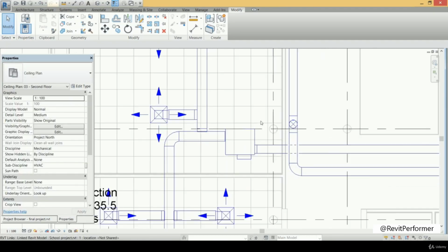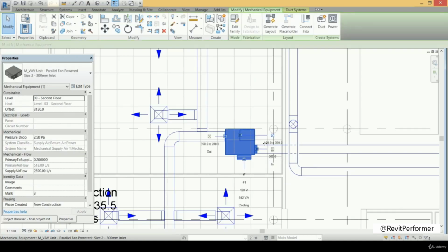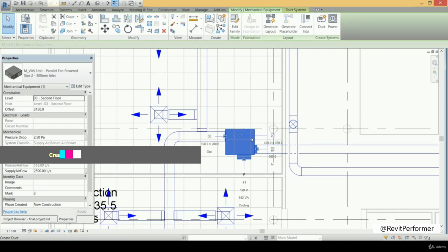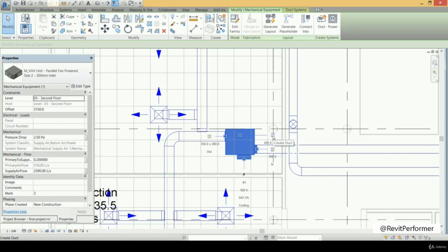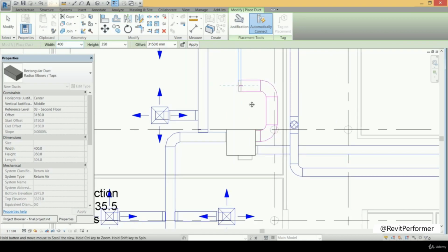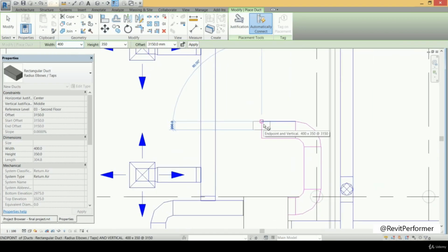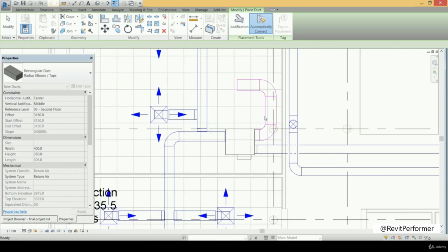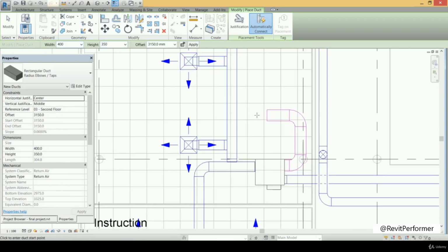And for that, the first thing we need to do is to go out of the VAV box with the return duct. So this is the input terminal to the return duct, and for that, we will press on that tab to go out of it with the required return duct. Here we can go until that point, and then we can move up. After that, we can go there. But you can see we have the same problem facing us, which is that this return duct interferes with that supplying duct.